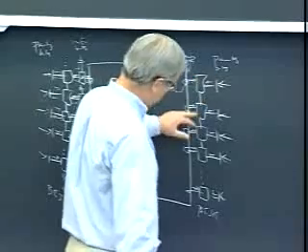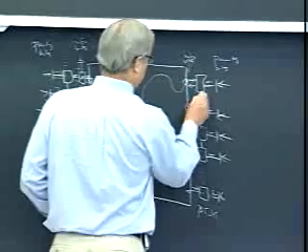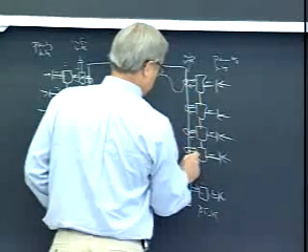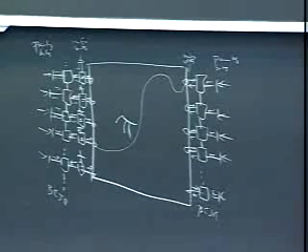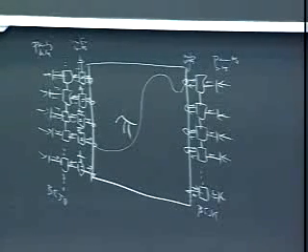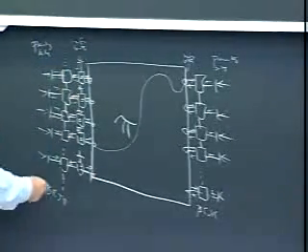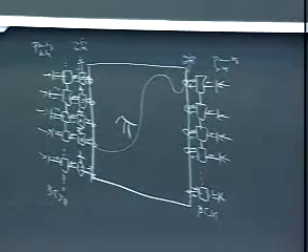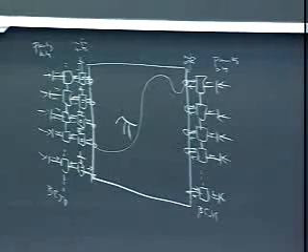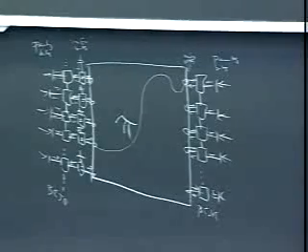You then do a complete sweep through 1,000 bits or whatever, and you develop outgoing messages here, which, let's hope, have improved the signal-to-noise ratio a little bit more, so that these are even more informative about the input bits. And they come back, and now with this further improved information, we can sweep through here again. That's where the turbo comes from. You keep recycling the information from left to right, from right to left, and hopefully you build up power and lower the signal-to-noise ratio each time.